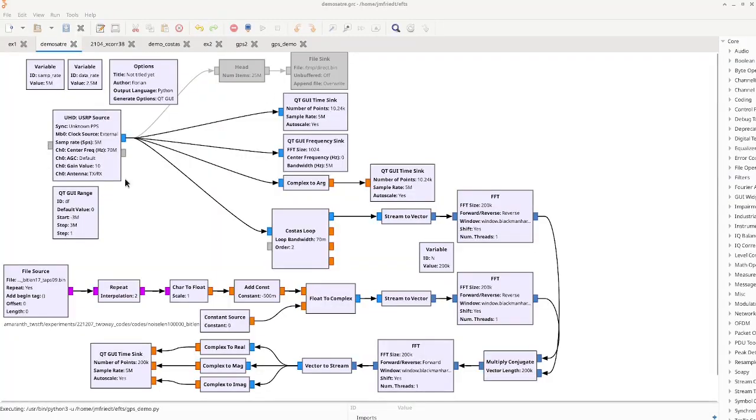So here we have the software-defined radio source, which is a B210 SDR, and because there is a hardware clock driving the flowchart, there is no need for a throttle block this time. We're going to look at the time output of the B210 signal in the frequency domain.